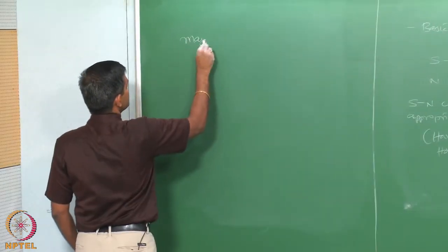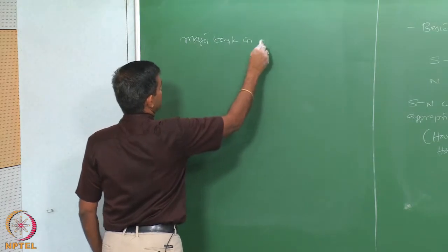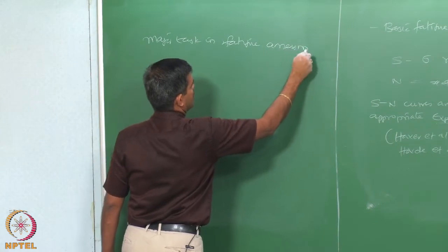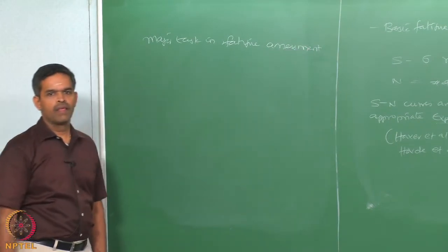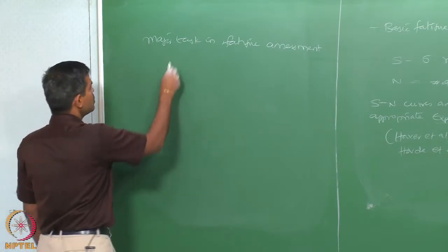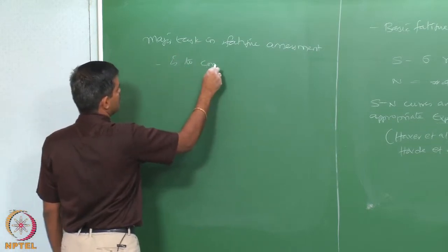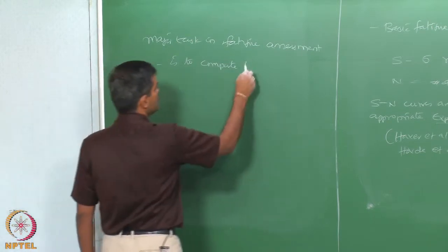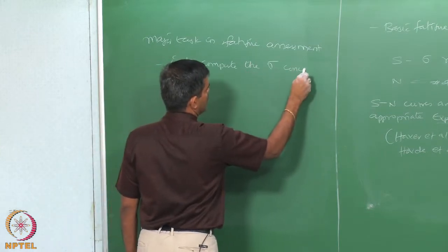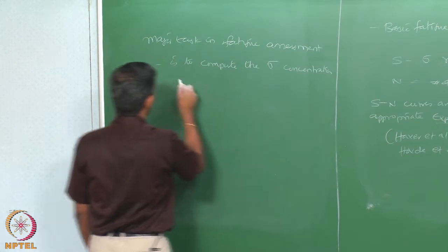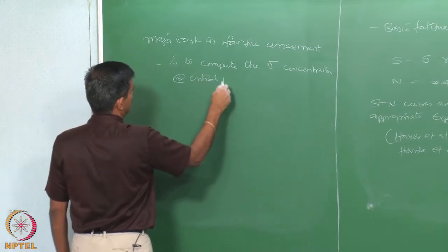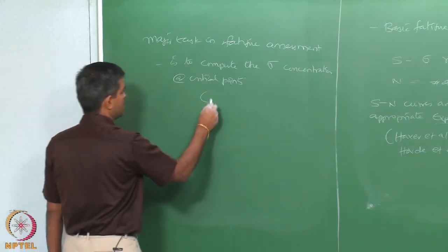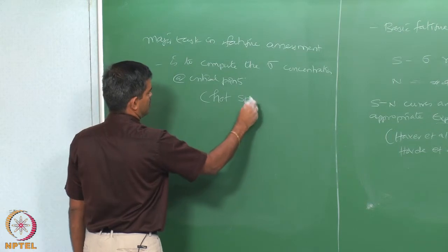The major task in fatigue assessment is to compute the stress concentration at critical points, what we call as hotspots.